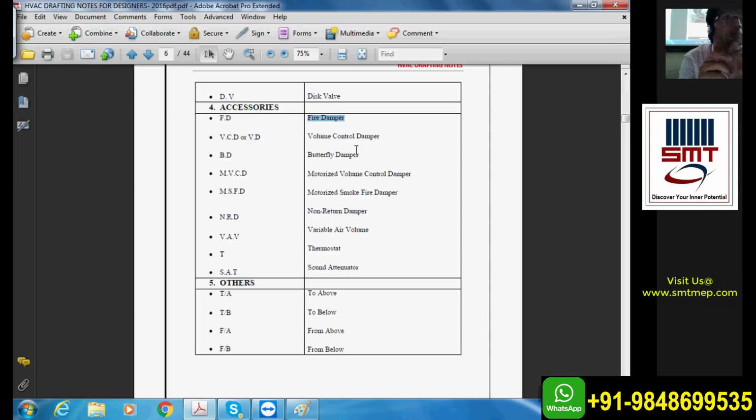And what is the VAV going to be attached to in the individual zone space? नहीं, यहाँ पर अब मैंने VAV box का कुछ एक wire छोड़ा है नीचे. How do I access a temperature of one particular zone? Thermostat. Right, a thermostat has to have a sensor connection to the VAV. That is how it will try to carry out the variation. ठीक है, तो there is a thermostat that is going to be a part of VAV box. And lastly you have a sound attenuator to reduce the sound.